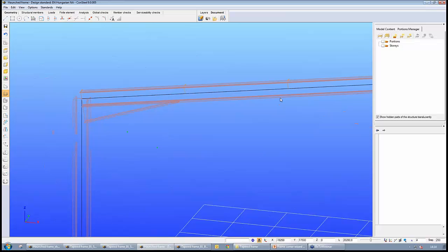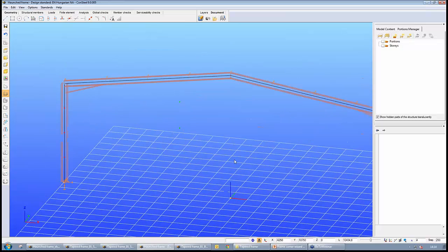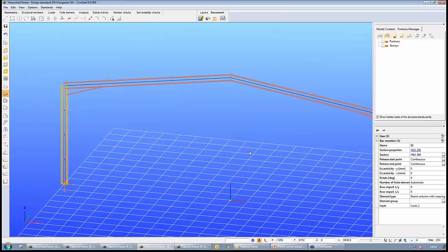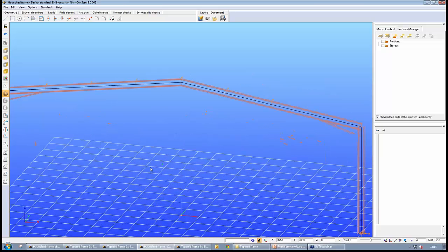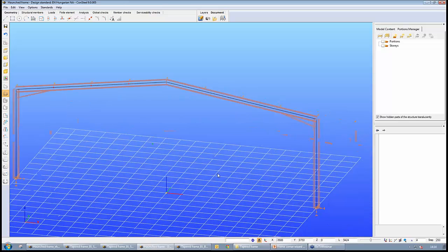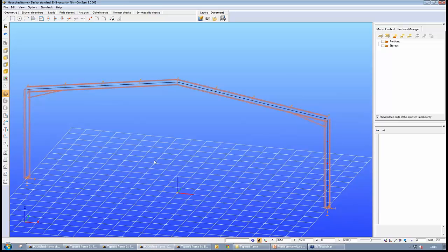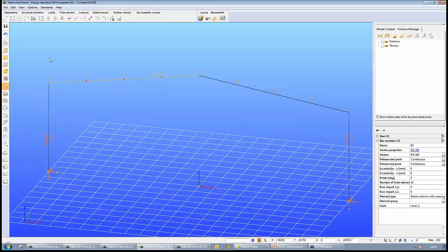So this is the classical beam model for this hinged frame, using some AGA section for the column, IP for the beam, and some hinge here, and it is fixed at the bottom, and we have some top flange restraints perpendicular to this frame. So this is a usual frame model in ConSteel consisting of beam elements. This is a line model.